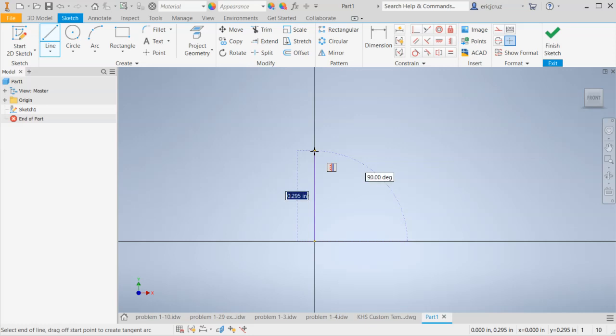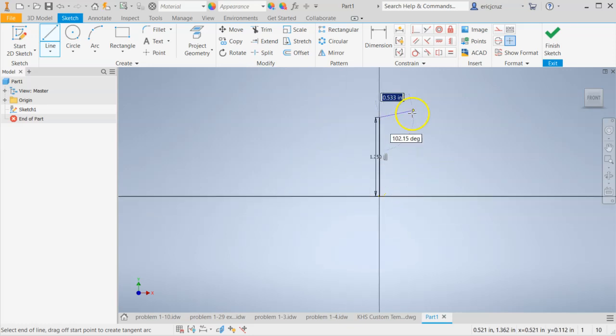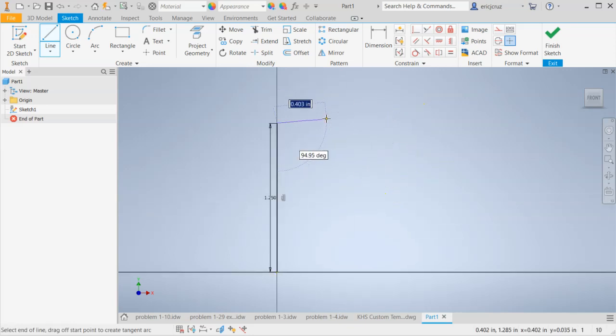Okay, we want to be on the left side here where the inch is, not the angle. So I'm using the Tab key on the keyboard. And on my technical drawing that I've created, I have 0.75 and I'm going to add plus 0.5. And I press enter, and then we get the length that we need for the height there. So that turns out to be 1.25 inches.